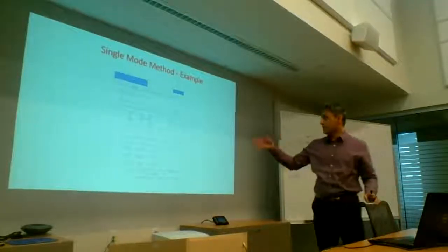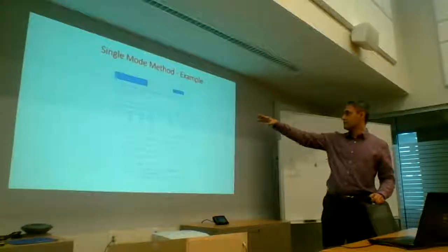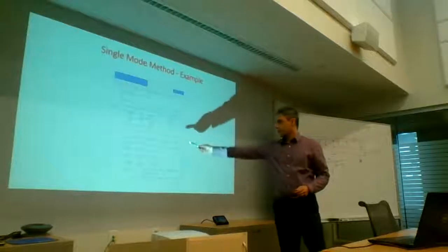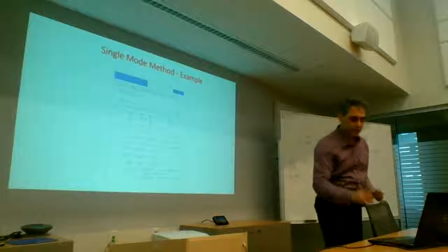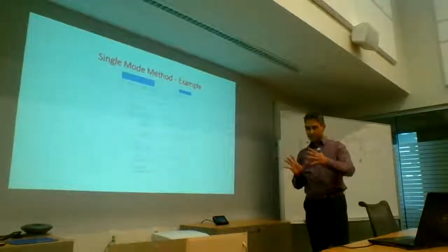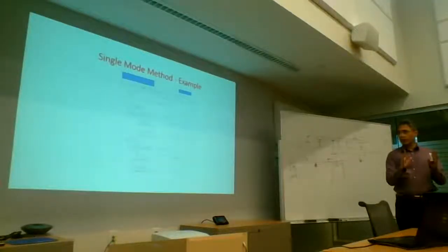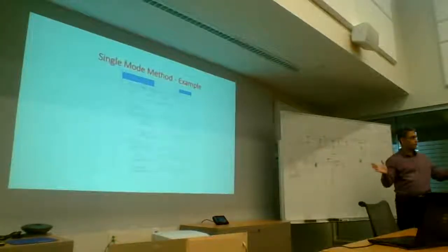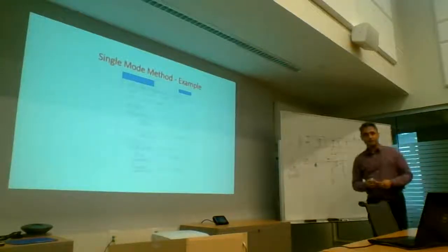Okay, so here is again an example. I've got 3 girders plus some deck and some asphalt on top. I've got the total lengths, so these are different length spans. I've got the heights, etc. So all the data is there. I've given different weights for each section because, as the bridge, to make sure that we utilize the material properly, we don't use the same girder sizes everywhere. We optimize them as best as possible.